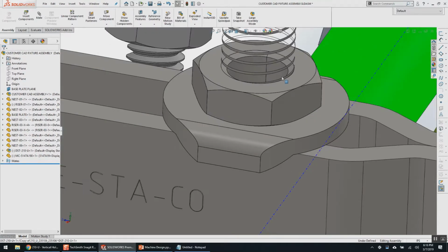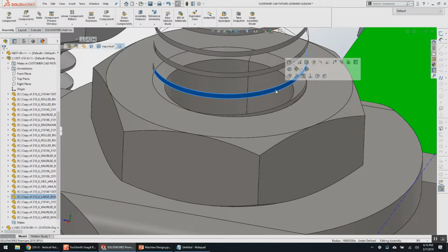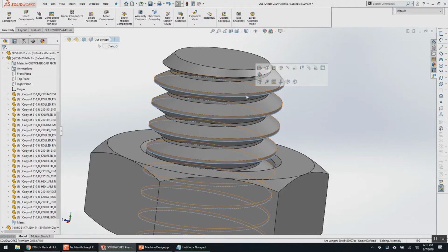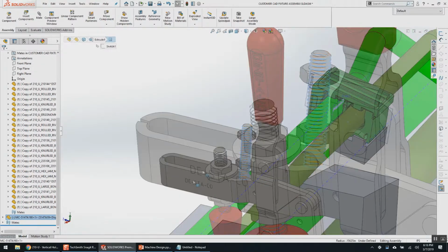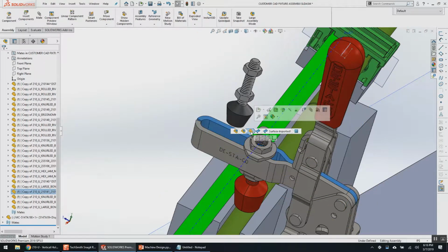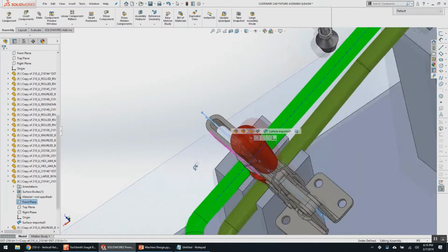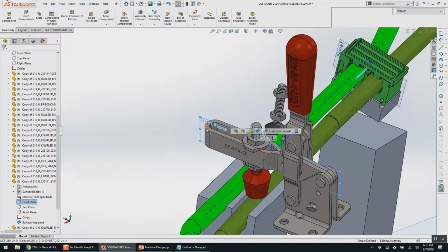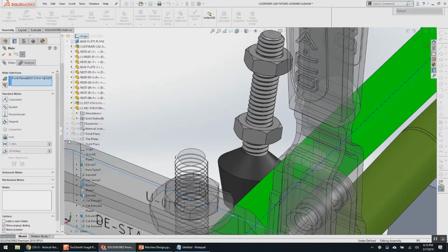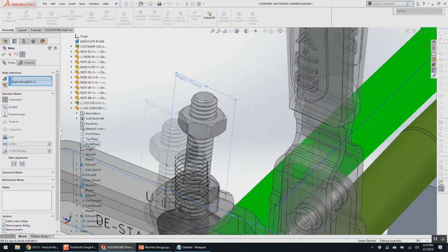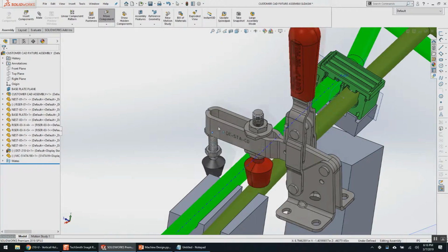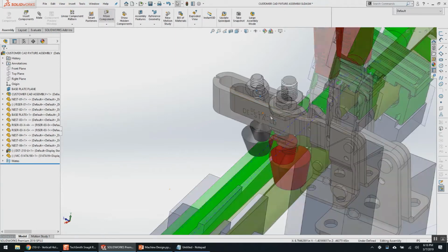Now let's insert that McMaster item. Looks like it's a smaller thread there. But it looks like this thread is kind of too bad. Radius, yeah, whatever. We'll throw it in there. So now I just gotta find the center plane. So let's pick on this, pick on that part. It'll allow me to pick a plane from breadcrumbs, which is super awesome. Let's hit mate. Let's expand this McMaster item, find the same plane.